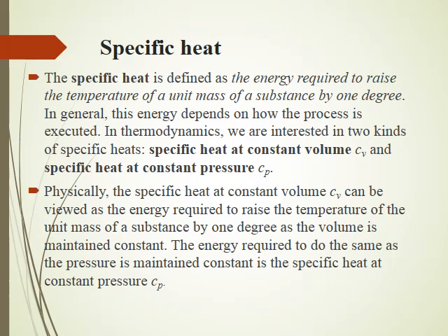Now we want to express the specific heats in terms of other thermodynamic properties. So let us assume that we take up a fixed mass in a stationary closed system and say it is undergoing a constant volume process. When it is undergoing a constant volume process, it means no boundary work, no expansion or compression work is involved.